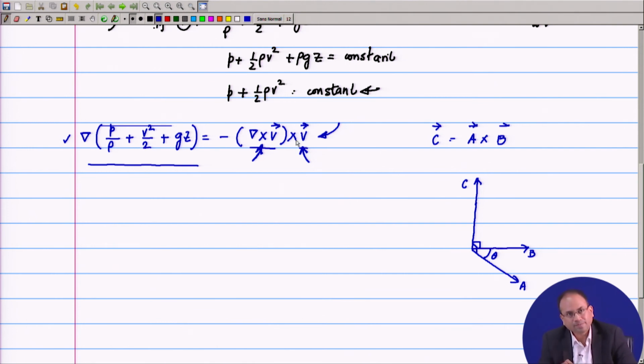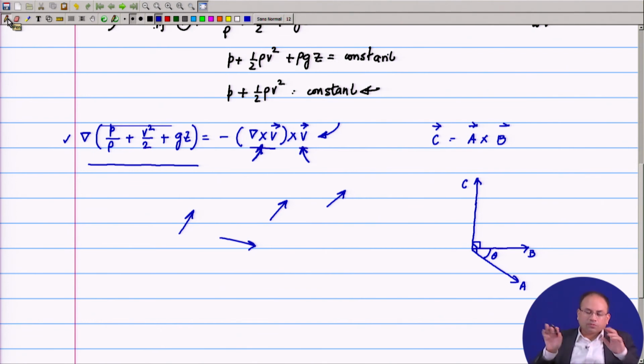the velocity vector. Now, the streamline, so suppose in a flow field, these are the instantaneous velocity vectors. I am trying to think of the resultant streamline, so that it does not become too difficult for me to draw. So, suppose these are the instantaneous velocity vectors in a flow field. There are many experimental techniques that can give you velocity vectors all throughout a flow field. For example, popularly there is something called PIV.